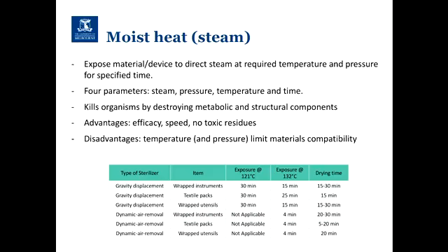The advantages of this are it's very efficient as long as you've got the right parameters. It's speedy, you can usually get a cycle done within a few hours, and there's no toxic residues. Quite often, steam sterilisation will be used for medical equipment, so your surgery equipment, that's often metal.